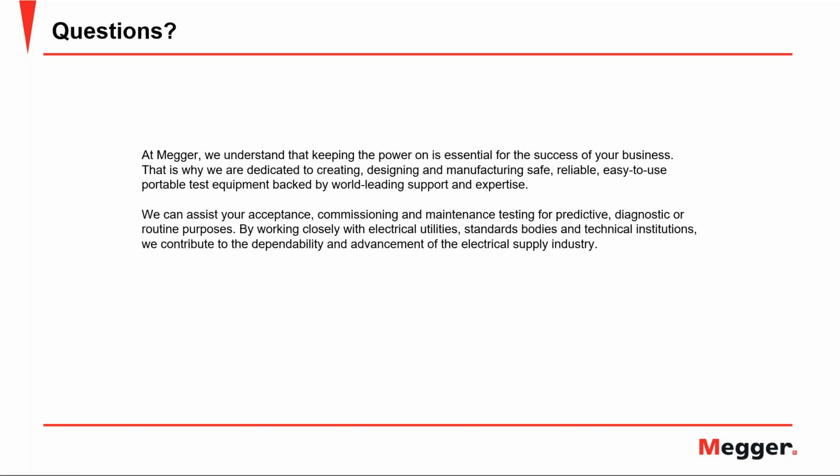They won't perform this primary injection testing on every single breaker, but they might perform it on a certain type or model of breaker, and use that as a reference measurement for all the breakers of that class and model. That's very standard. Usually you don't get the manufacturer's test results. Typically you would go and ask for them, and that's not very common.